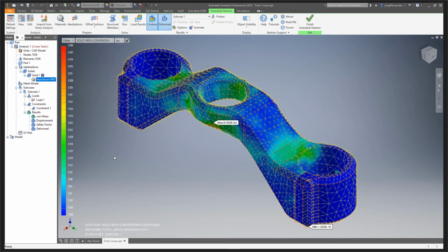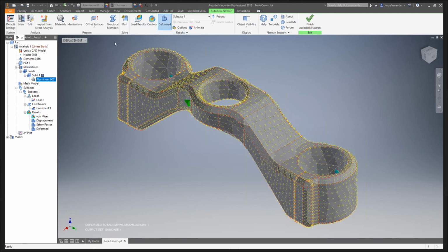The last question here on meshing. Are we limited to TET meshes in Nastran, or can we go like quads and stuff like that? Yeah, this just does TETs and quads actually by default. So we don't have the option to change it to bricks, for example. But really, when you look at some of the information out there, TETs are really one of the best ways to go for a lot of the cases. So where we do have flexibility is just changing the mesh size and saying if it's parabolic or linear. And we saw that when we went to the mesh settings itself.